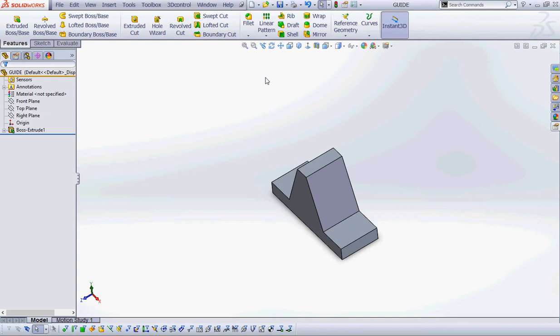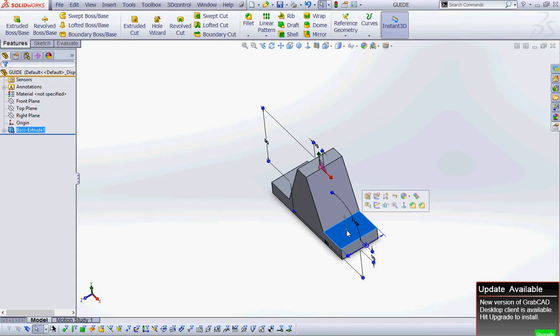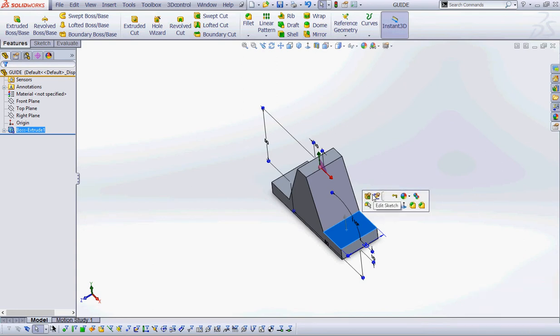Okay, so we're on page 1-97, and the only thing left is to do a base extrude. And Akita, if I had the same dimensions as you, but mine says underdefined? Maybe you need a coincident constraint between the endpoint of the vertical line and the origin, because that's the only constraint I added.